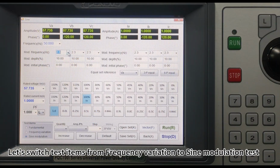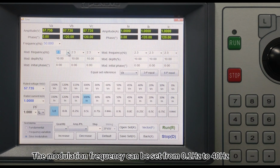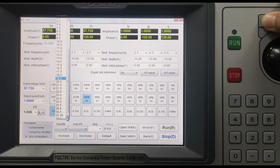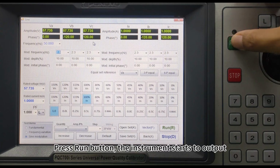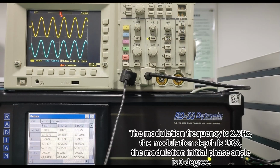Let's switch test items from frequency variation to sine modulation test. Sine modulation is used to generate modulated waveform. The modulation frequency can be set from 0.1 Hz to 40 Hz. Modulation depth and modulation initial phase angle can also be set here. Press run button, the instrument starts to output. The modulation frequency is 2.3 Hz, the modulation depth is 10%, the modulation initial phase angle is 0 degree.